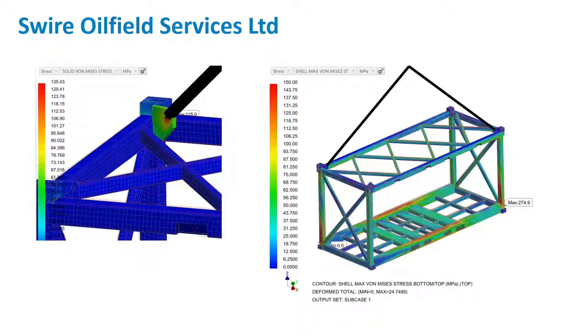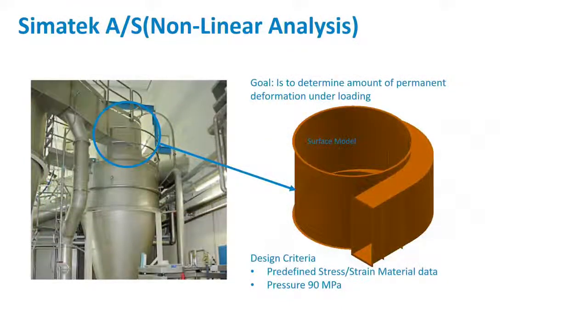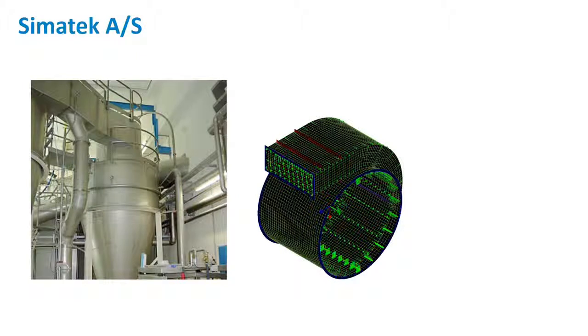And this is the corresponding stress plots. One more customer case, this is a plasticity analysis. It's a high internal pressure in this case, and the customer wants to see how big the remaining deflection will be. And as it's a thin plate model or a thin plate design, it is analyzed using shell elements. That can be done easily in both Inventor and in Nastran InCAD.